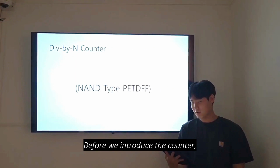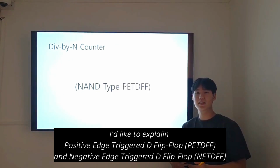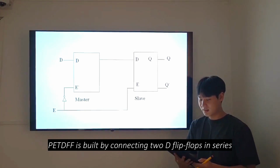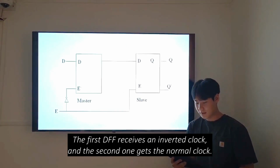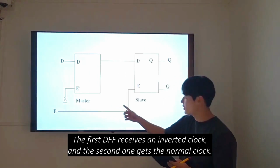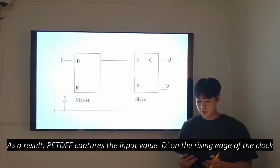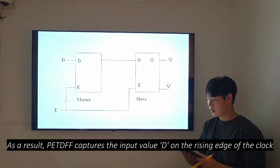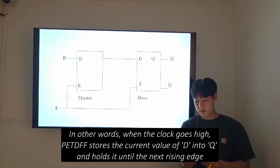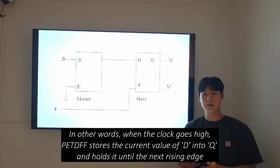Before we introduce the counter, I'd like to explain positive edge triggered D flip-flop and negative edge triggered D flip-flop. PETDFF is built by connecting two D flip-flops in series. The first DFF receives an inverted clock, and the second one gets a normal clock. As a result, PETDFF captures the input value D on the rising edge of the clock. In other words, when the clock goes high, PETDFF stores the current value of D into Q and holds it until the next rising edge.